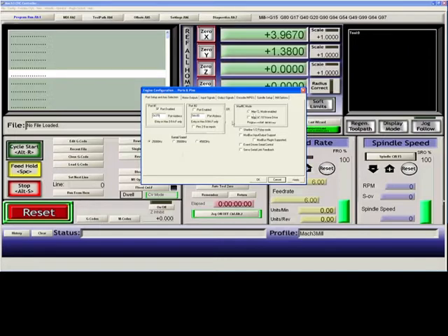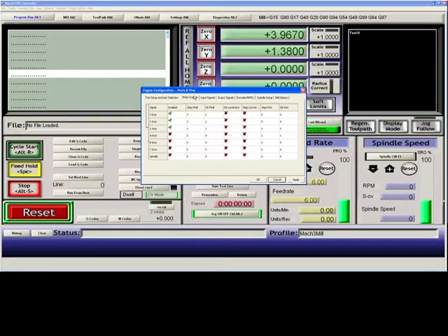So we have to turn it off. If we enable Mach3 wave drive, this causes 4 pins to go out the system for every pulse. The 4 pins would correspond to the 4 wires on a motor. So we've turned that off, and now we need to check our motor outputs.